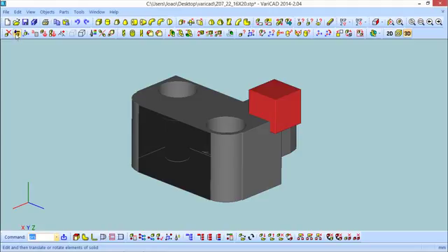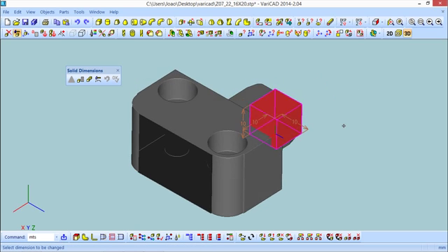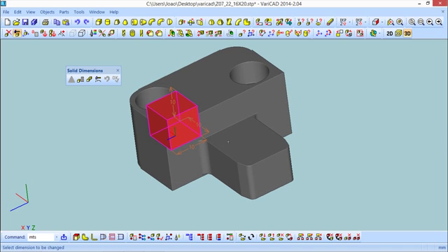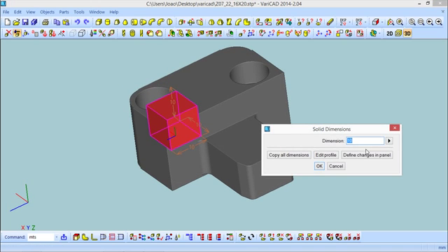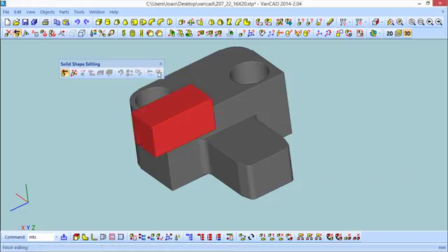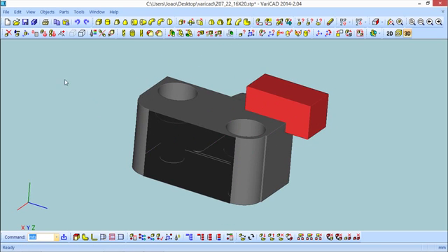Having some history on a solid, some tree of things, allows us, for example, to come and edit this solid. The edition allows you, somewhere in the middle of the events where you work with this, to, for example, edit a dimension and rebuild this automatically. This is the history of the solid.